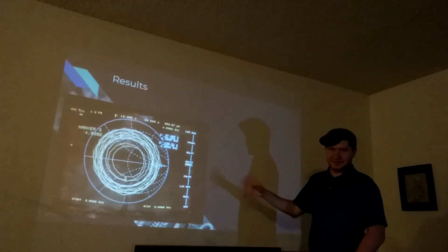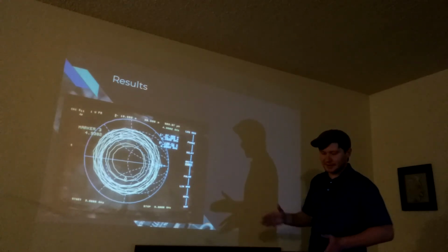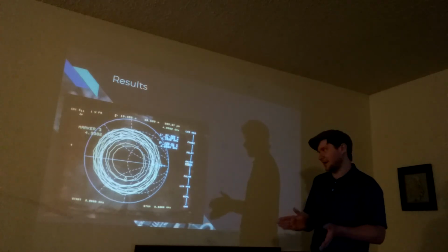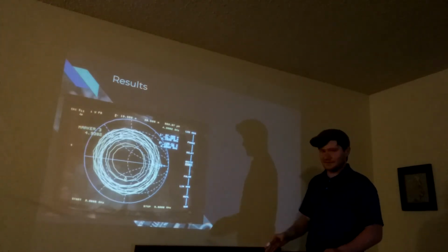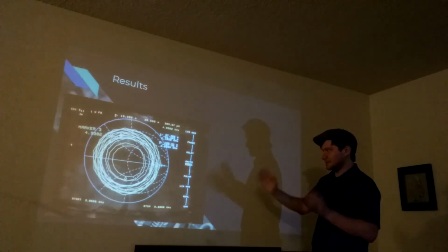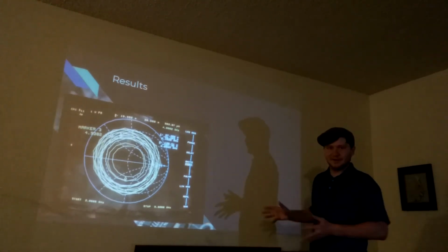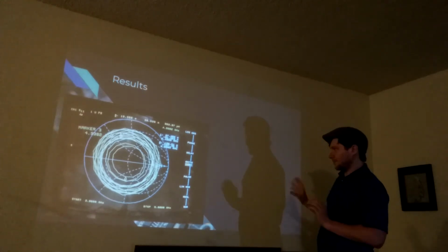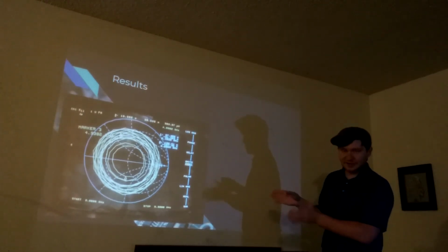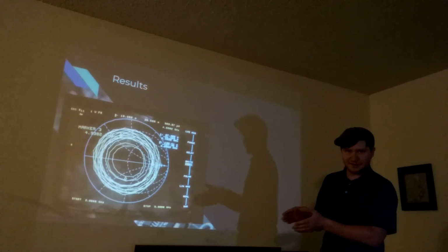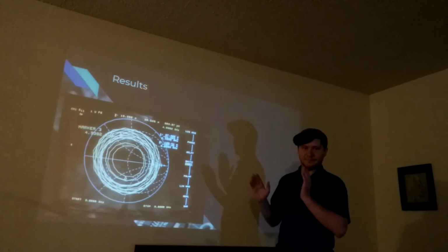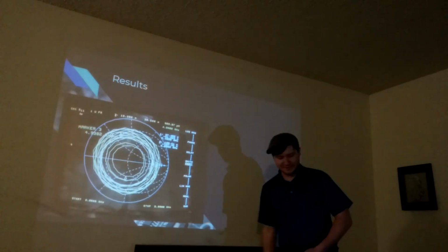So to me this means that with maybe a conical stub, I might be able to match this wide range of frequencies, since I'd just be matching one VSWR circle for a perfect antenna. However, for my specific antenna, I would probably try to match just the 2.4 gigahertz and just the 5, since that's what I was going for with my personal home project.